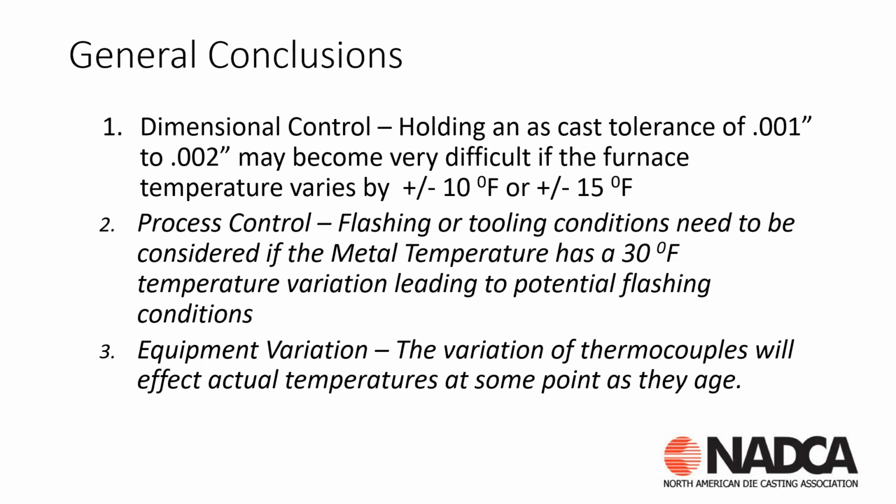For the process control, I touched on this a little bit, but if our metal temperature is changing, then our die physical attributes are changing. So all of a sudden our slides, if our slide is being cooled and the retainer around it or the cavity around it is being heated up dramatically, that could create fitting conditions. And if the slide's not fitting correctly, if the cover and ejector are not coming together correctly, then we could start to see potential flashing due to temperature variation.